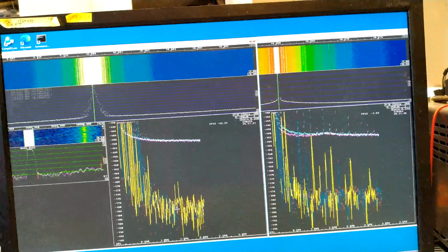After nearly 4 hours, the SDR-IP seems to converge towards minus 182 dBc per hertz, and the imaginary part is significantly below the yellow trace. On the sound card, the result is similar, close to minus 182, but there is a spur which comes negative in the real part, and the imaginary part is not well below the yellow. But maybe it will go down. I will see tomorrow. 50 hours.